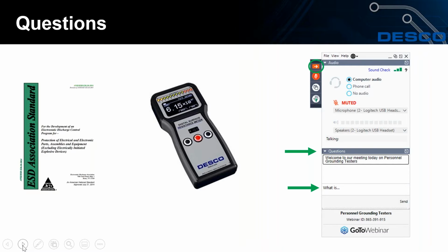And so, as an example, if I wanted to qualify ESD mats, I need to have multiple sample sizes. I need to control temperature and humidity, and then I go through the proper, fixed qualification process as far as where to put my weights, voltage, things like that. But after I install that product, let's say an ESD mat on my work surface, now it becomes compliance verification. So everything else is good. I just need to know, for instance, what the resistance to ground is of that material. And that's one of the things I'm going to show you.